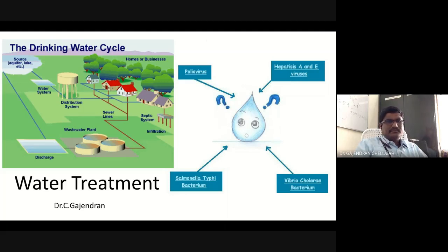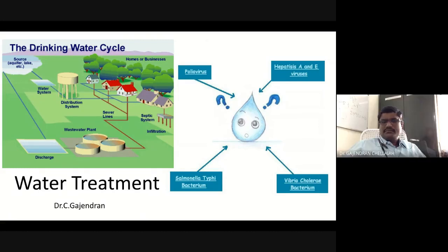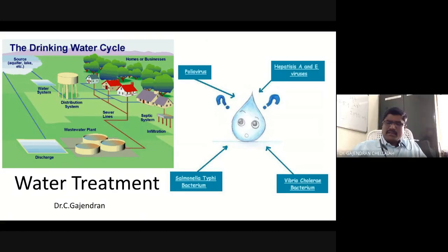Satyan, what water quality parameters have you come across? Suppose I want to check the water quality, what are the parameters you give importance to, based on your understanding? These are all the parameters we are supposed to test for water. Sir, first pH, sir. BOD, COD, and temperature, sir. Dissolved oxygen, and salt content, sir. Hardness. Salt content, okay, hardness.